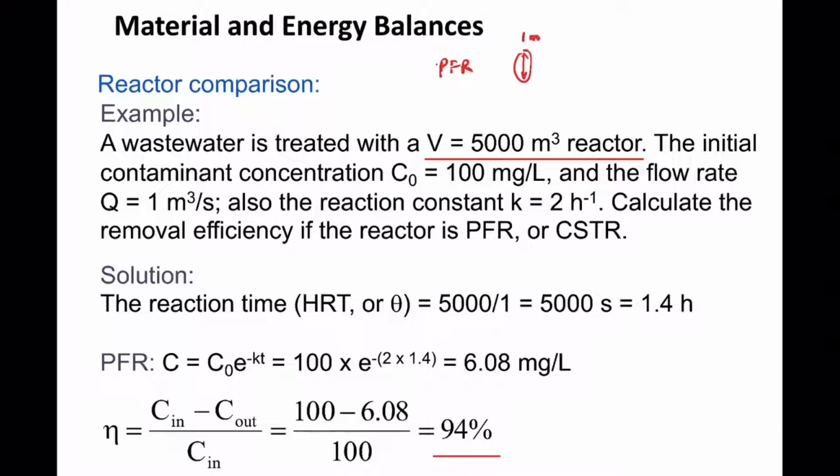You can see that the length of this reactor is going to be kilometers long. It's very difficult for us to make a water treatment facility that's composed of this very long tube that acts as a reactor, right? It's very unrealistic to do that. So that's why you can later see that for a lot of these wastewater treatment plants, most of them are actually CSTR, okay?